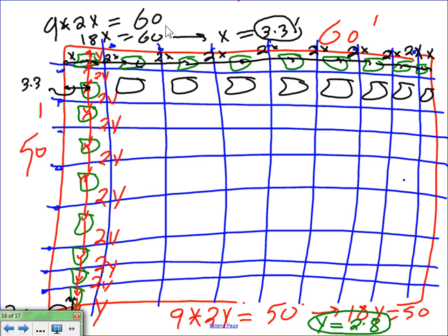Why do we identify if you have two voltage systems in a building? This is a simple answer actually. If you have two voltage systems in the building, by code you have to color code all the conductors of the branch circuits and the feeders for the two systems, 480/277 and 208/120. Why do you think we care? Anybody know the S word? Safety. The last thing you want to do is take a phase A from 480 and tie it to a neutral of the 208, and you get some weird voltage, a burn equivalent.